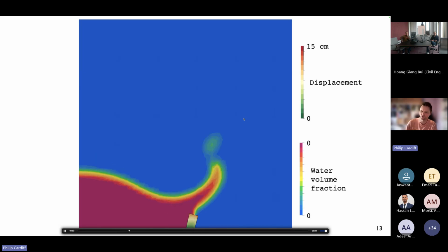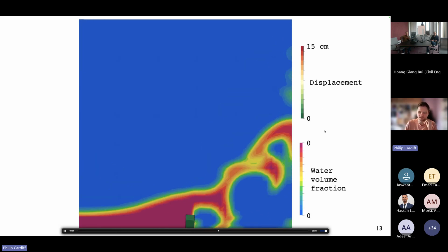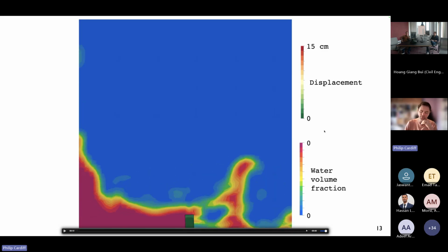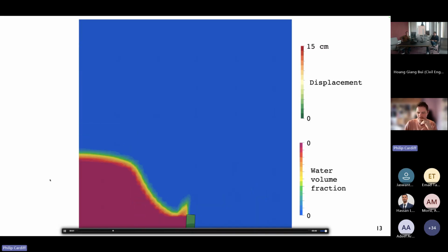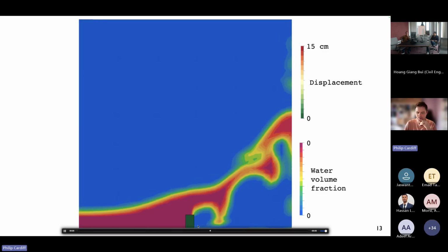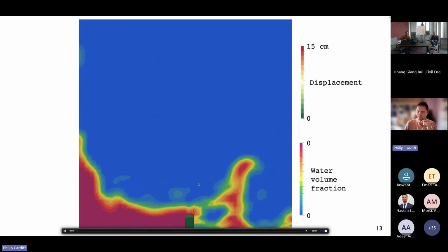Towards FSI, and I know there will be talks on FSI as well, and this solids4foam has been mentioned. So if you're from a CFD background, you may be familiar with this dam break case where you have a rigid little block and then a column of water drops and hits it. And then there's an extension of this benchmark case where you have an elastic beam as well. So this is a multi-phase FSI problem. You can solve this, for example, in the solids4foam OpenFOAM toolbox.